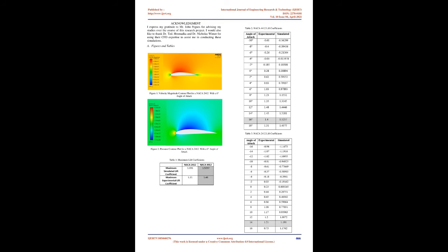D. Validation. Validation is another important step in the simulation process and determines if the simulated results agree with physical reality. The results show agreement with this principle. The contour plot has clearly defined low-pressure contours above the airfoil. Further, the leading edge contains a point of high pressure, illustrating the point before the fluid flow divides into two flows. The pressure distribution of the NACA 4412 is consistent with the known properties of airfoil pressure.